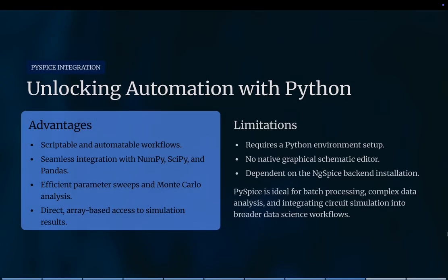And the next part is introduction to PySpice. Let's briefly look at PySpice, which is a Python wrapper for Ngspice that enables automation and advanced data processing. Here's the same RC filter in PySpice, in which you can see the code here. And extracting the results is quite simple, and you can also see the Python code here again. And this shows the Bode plot output.